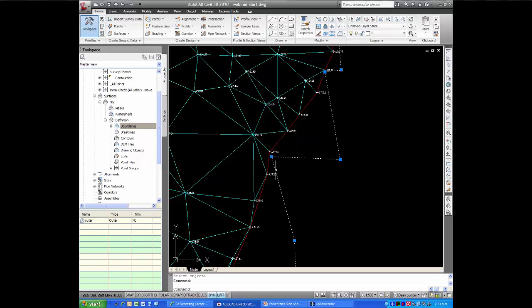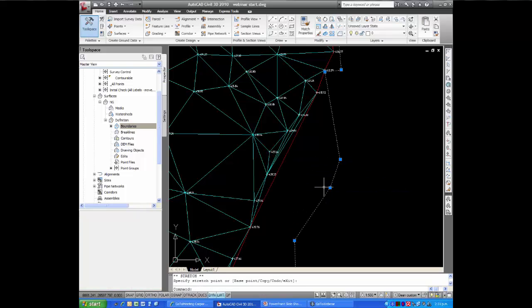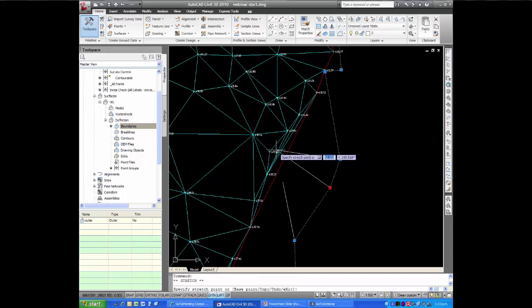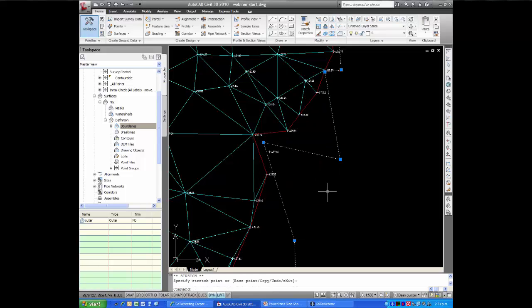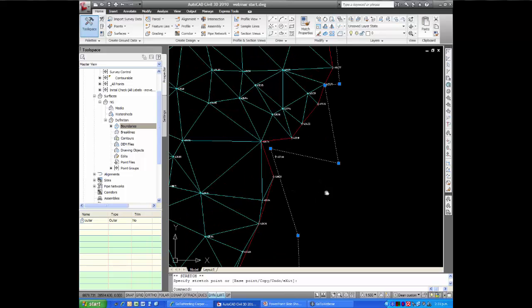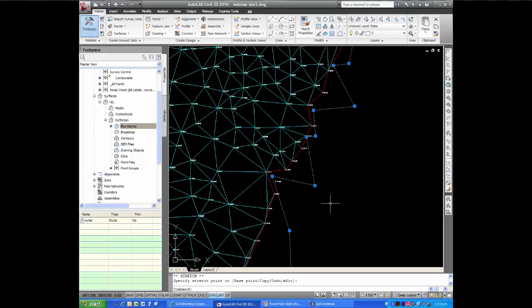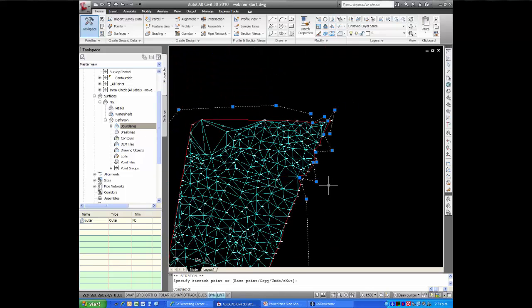The fact that it auto updates means that I can grab that polyline now and change it, and suddenly those triangles will come back again once I've done that. Just let my screen catch up. And similarly, I can grab that polyline and put it back and cross it over more triangles if I want to eliminate all of those ones as well out of my surface. Okay, so it's all automatic update, a parametric type program.